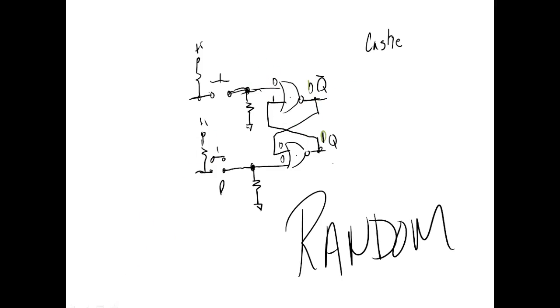Well, we could, because an open input of a basic gate is usually assumed as a high, right? So we could leave it floating, but any good engineer would never leave an input floating. That's like Marines never leave a man behind, right? So a good engineer would never ever leave inputs floating. So we got two options. We could come over here and I could do this.